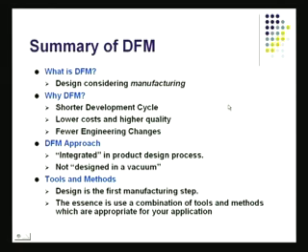So what is the summary of DFM? If we summarize this very quickly, it is design considering manufacturing, because my eventual goal is to be able to manufacture that product. What are some of the advantages? We will end up with shorter development time, lower cost, higher quality. These are some of the things coming out of this. And there will be fewer engineering changes, which will not be there if you do not go the DFM route. The approach itself is integrated, and of course, this is not designed in a vacuum. You've got constant dialogue going with the manufacturing unit. So you've got to make sure that you maintain this so that design problems are not discovered when manufacturing gets into the act.